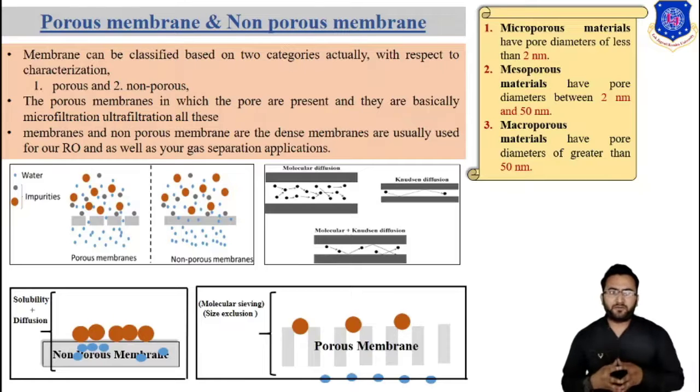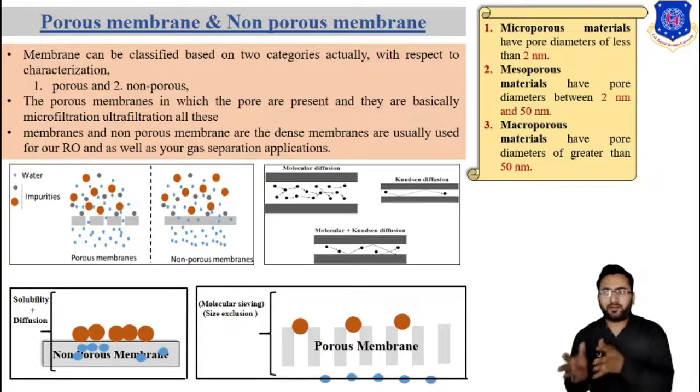Now in microfiltration and ultrafiltration membranes, fixed pores are present, which can be characterized by various techniques. The pores are already present and fixed, so we need to characterize them, and they are distinctly visible under different techniques. In order to avoid confusion in defining porous membrane, the term porous has been used throughout this course for both microfiltration and ultrafiltration, instead of frequently using the term microporous. This definition of porous is more in agreement with the definition adopted by IUPAC.